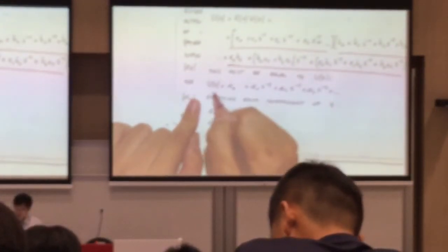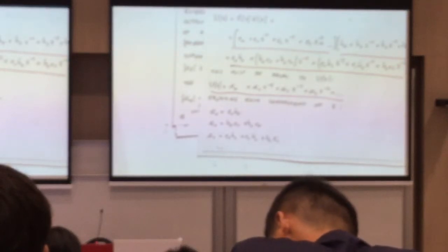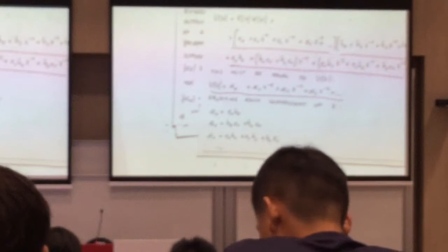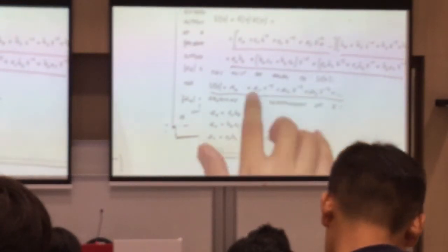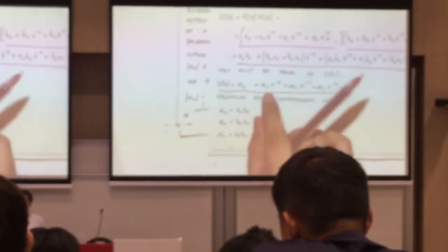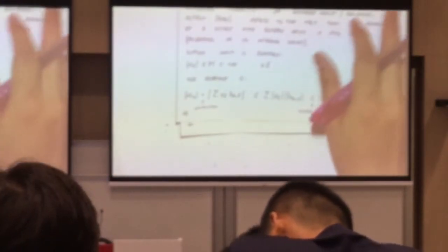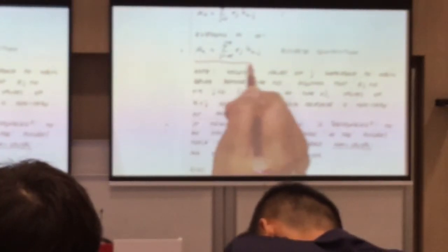Then your output is supposed to be a recurrence equation. As we described before, your output should be a certain function of your past outputs, your past inputs and your current input. So this should be the final solution. If you do the mapping, you will notice U0 is equal to this one, U1 equal to this one, U2 equal to this one. Don't forget, U(Z) is also the Z transform of U(k). If you do the Z transform of U(k), you get this one. So they must have a certain mapping. This bears the convolution path. So eventually, each of your U(k) corresponds to the discrete convolution.